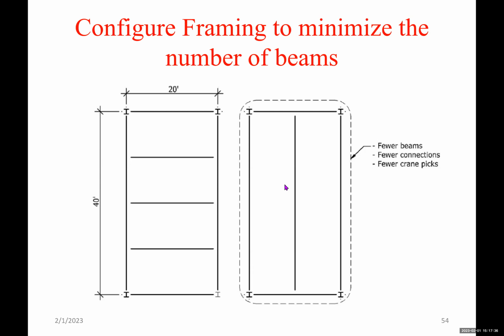Yeah, it's a service, but eventually you are responsible for that. So you can give the fabricator a schematic of how the gusset plate should be, and let the fabricator run the numbers. You have to give him the forces. That's fine. But schematically, you have to do that.